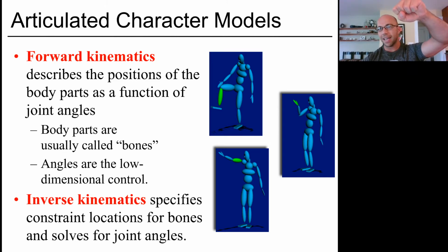And then the IK problem says, what joint angles do I need so that my hand ends up at a particular location? What we're going to see is that the forward kinematics problem is relatively easy computationally, and the IK problem, the inverse kinematics problem, is relatively difficult. It's going to require nonlinear optimization. So we're only going to touch on it in this course, and I'm more than happy to point you guys toward resources to tell you more.